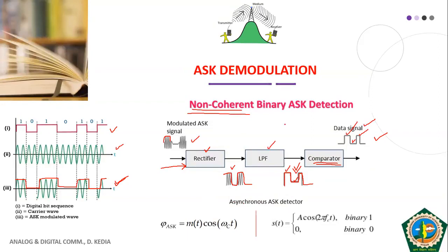Obviously it is not the complete binary ASK detector. We will need to convert my digital signal into an analog signal if it was an original analog signal. If it was an original data signal generated by some computer directly, then this is nothing but the original data signal. Here you can see that I have not generated any carrier locally at the receiver side.